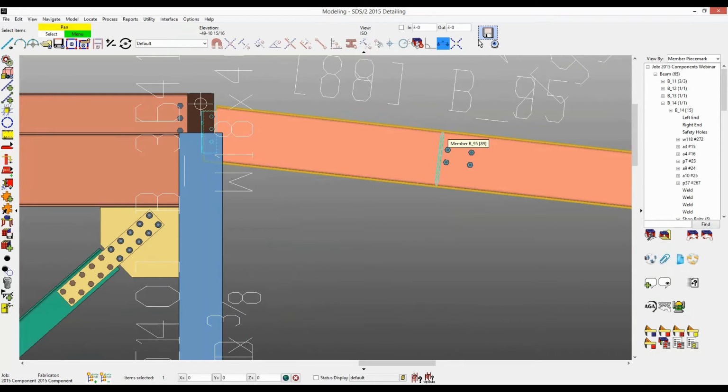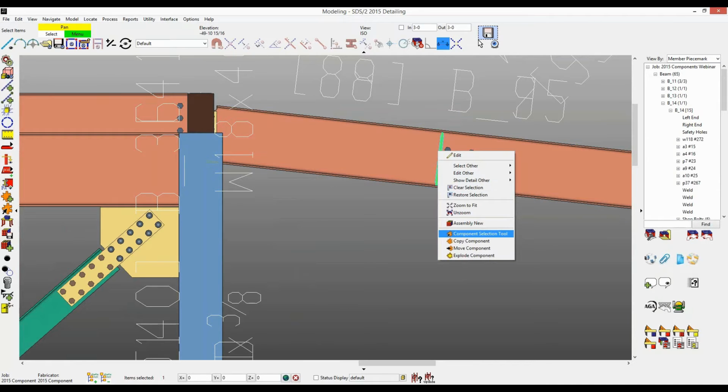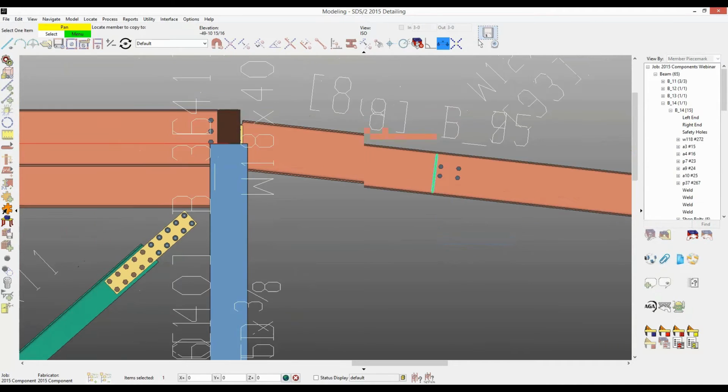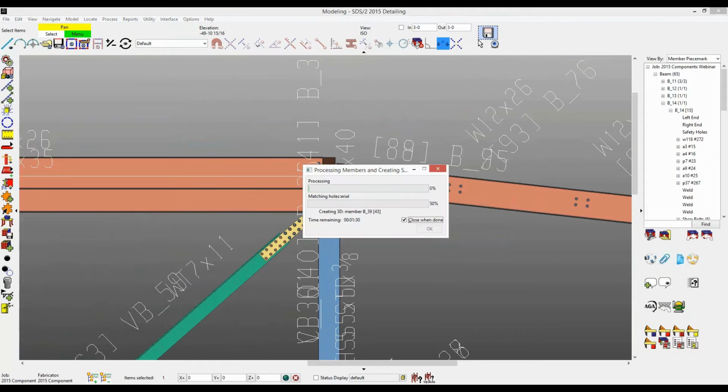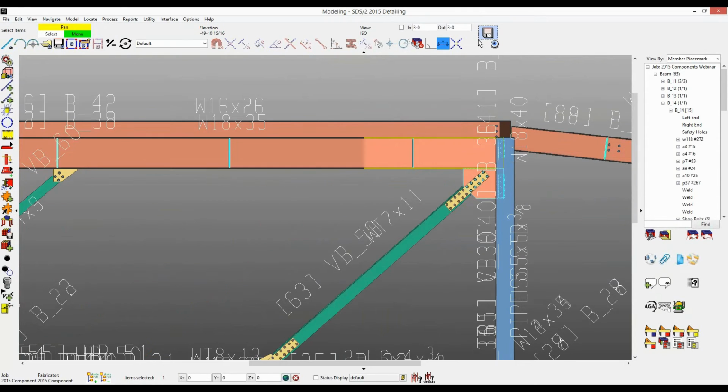Now, normal on a completely flat beam is going to be vertical as well. So if I would go ahead and copy this one, let's just right-click and copy, and let's copy it to right there. We'll go ahead and right-click and say OK, reprocess that. This is set to normal, but it did keep it vertical because that's a flat beam.